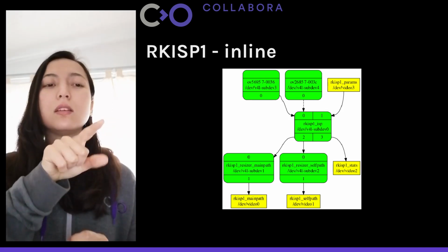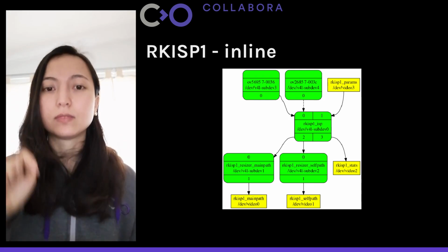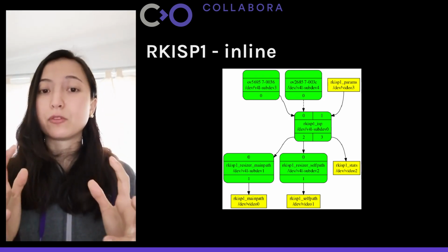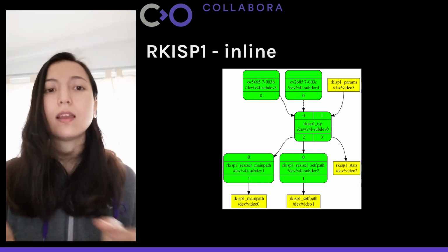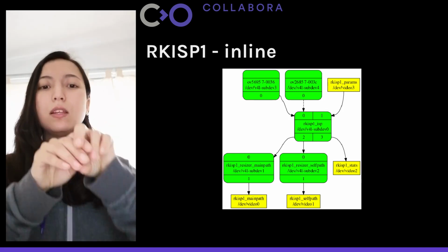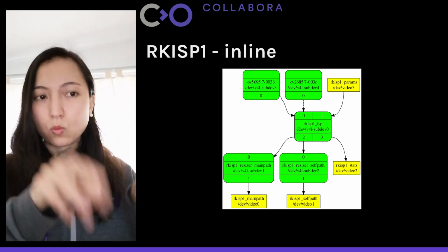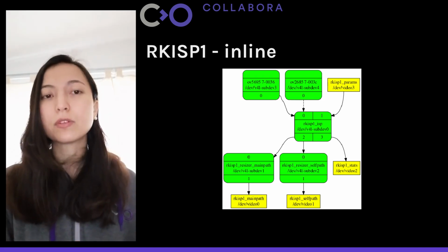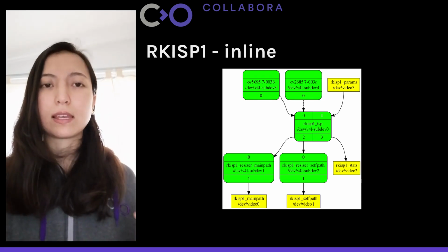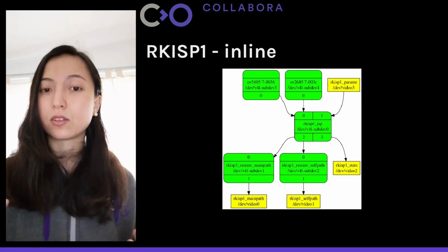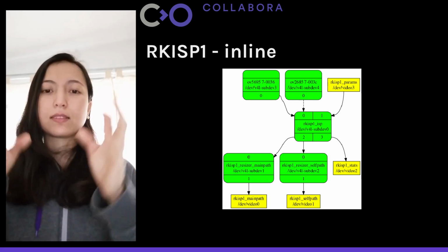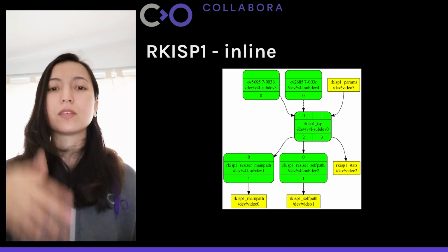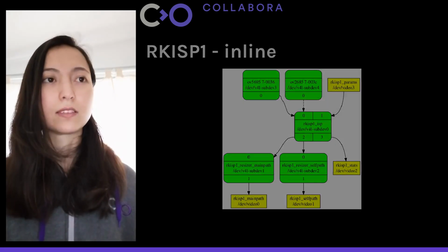That's why you see one line is dashed. The ISP performs some kind of processing, and it outputs the image through one of those 2 paths, main path and self path, as we mentioned before. And this driver can also do something similar to the Intel driver, generating statistics and receiving parameters from user space.